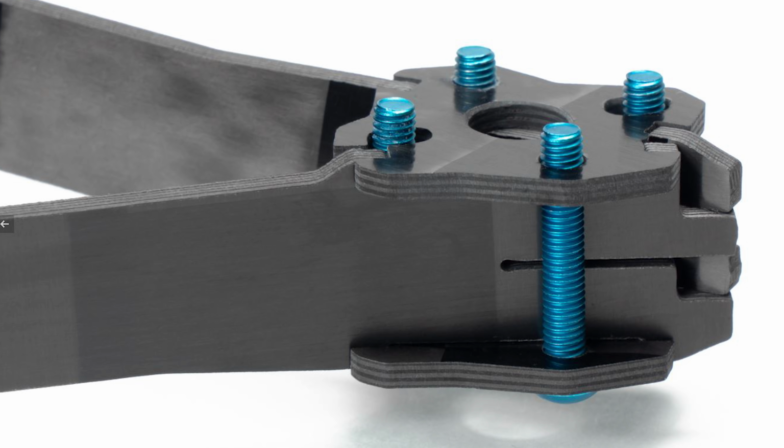So then why are you using a water cutter? That's not a reason. We're using it because we have vertical arms, so we have slots where these arms go into the plates in the middle and out of the motors. And we want this big contact area between these parts as possible. And if you do this with a mill, you need to make what we call a keyhole or something like that. Right, keyhole shape, because you have a radius on this mill. Okay, so let me explain that part.